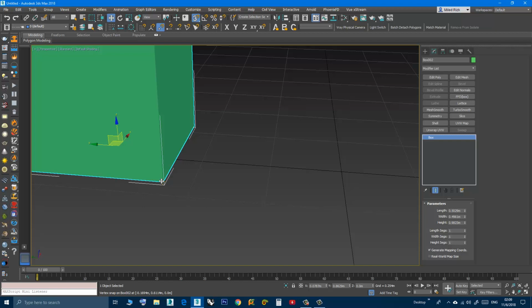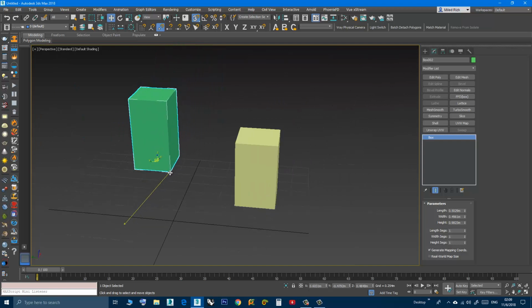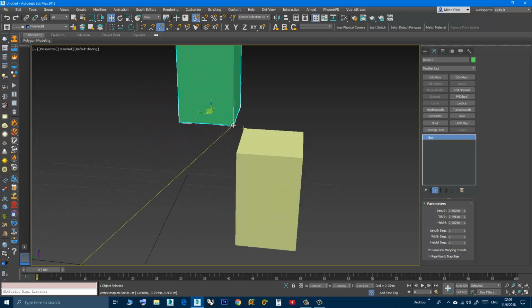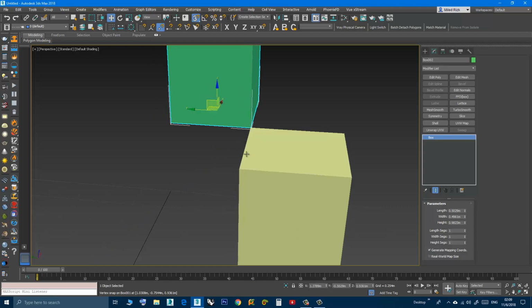When you see the mouse icon change to move, and at the same time the vertex snap is flashing, just click. Now you are holding the object by this vertex. Now approach this vertex, and as you can see, the other one flashes. You don't need to get any closer, just release the mouse button now and it snaps.